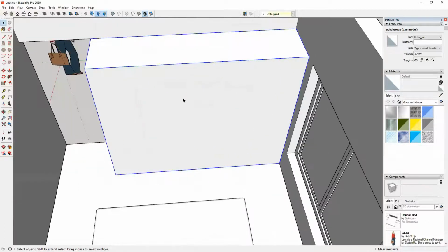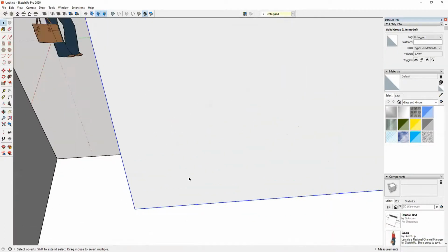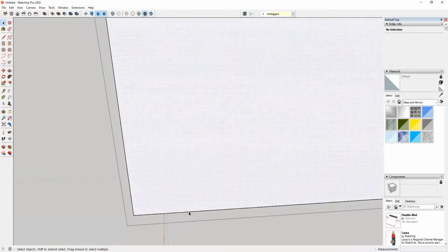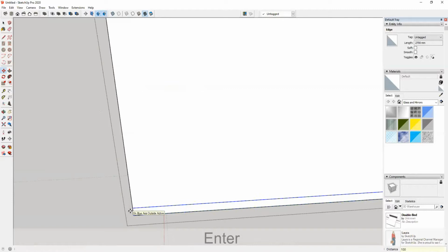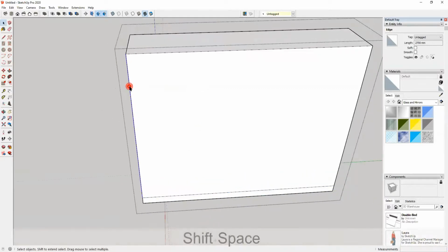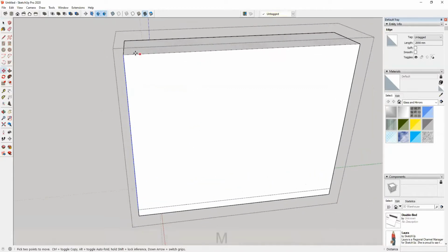Let's add a few details here also. Let's start with this 100, and the remaining part will be divided. So in order to divide the face, I will use the divide tool. If you remember, we can divide a particular distance by a number of divisions.